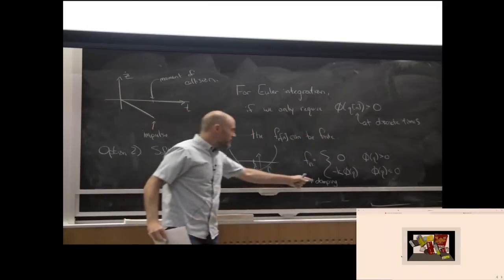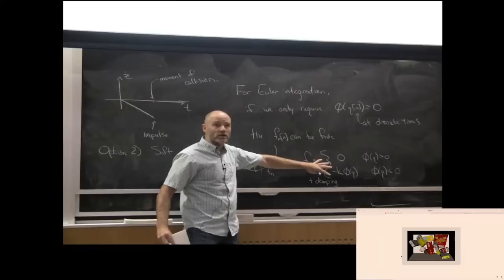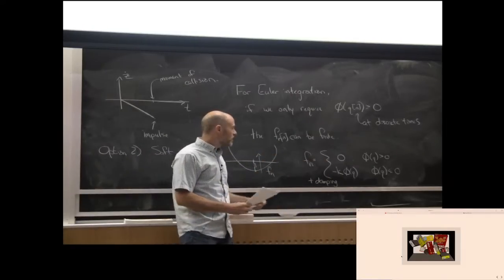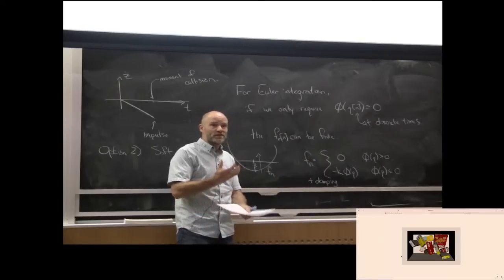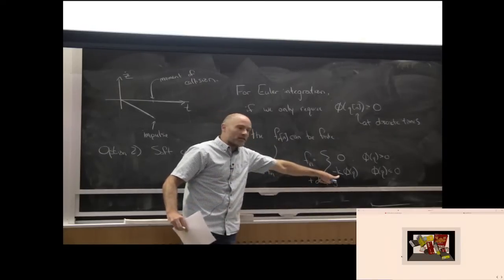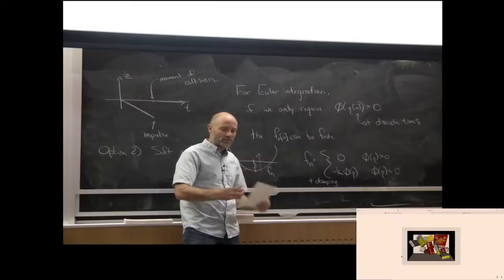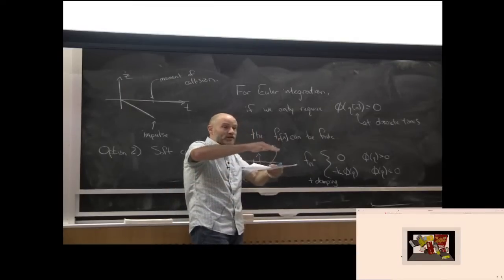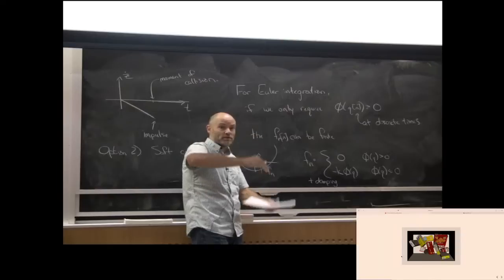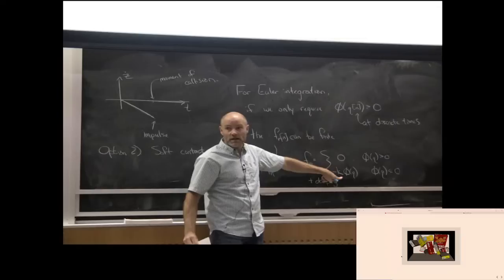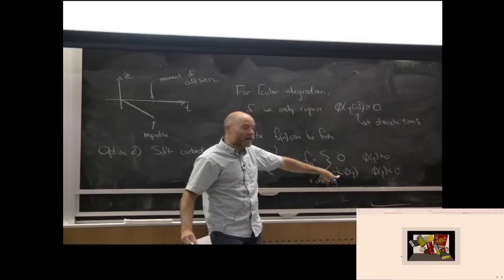This is actually, I would say, a better model of what really happens in the world than rigid objects. No objects are technically rigid. But to simulate accurate things that don't penetrate much, like imperceptibly, right? When my foot's hitting the ground, there's a small deformation of my skin, but not a big deformation, which means in order to model that accurately, I have to choose k to be very big. And this is the tension, right? Now I can add stiffness in my contact model, but it means I have to simulate slowly.